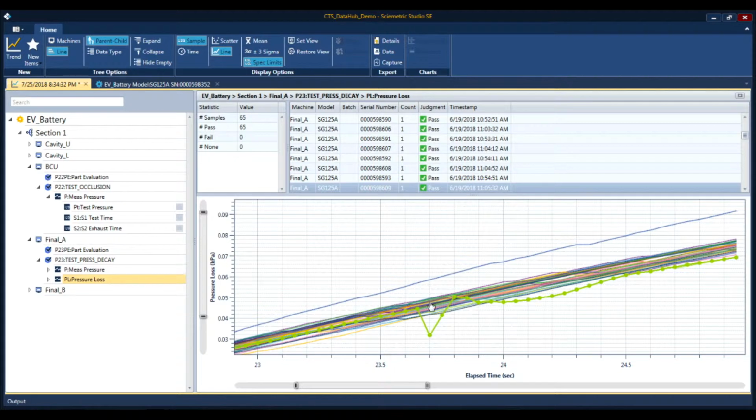In leak testing, an outlier like this can represent important issues, such as a seal moving on a pneumatic ram that's clamping the part, or something mechanical in the part, like a spring or check valve, releasing air from a trapped cavity back into the test cavity. Others can represent slight shocks that cause movement of the part.